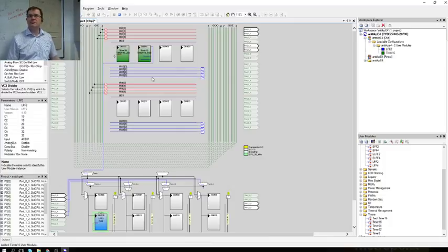Any questions? Timer setting? Well, it doesn't matter what kind of interrupt you use there, since we are not using the interrupts. But you just select something so that you don't get the warning. Got it? Good.